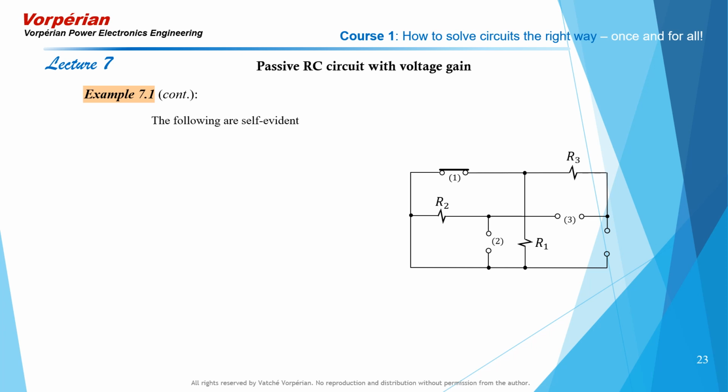We shall now see that all the driving point resistances are trivial and can be determined by inspection. Let us go to port 1 and determine the driving point resistance looking into port 1 while ports 2 and 3 are in their reference state. This can be seen to be given by R1.